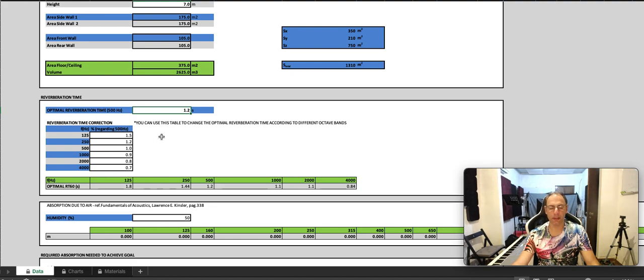So usually there's a longer reverberation time in this kind of room. So at 125 Hertz, we increase the reverberation time by 1.5, and then we are decreasing the reverberation time at higher frequencies because, of course, this is a large space, and the air enclosed inside the room will absorb the sound as well.